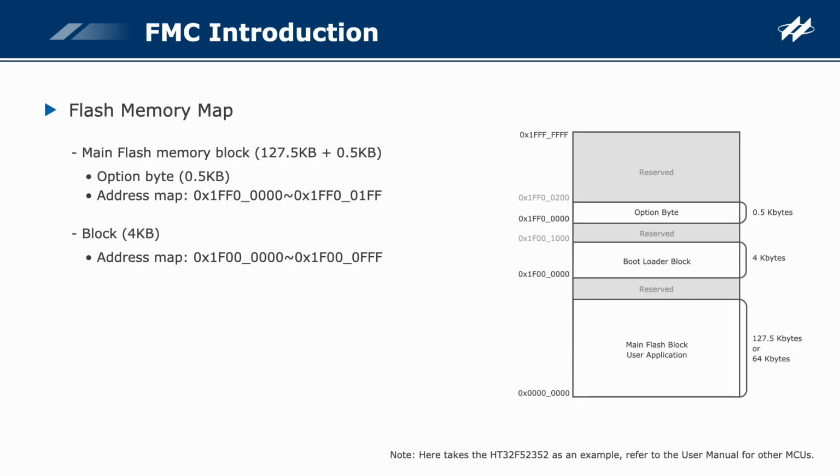As we know, the HT32 MCU address ranges from hex 00000000 to hex FFFFFFFF, 4 GB. Different MCU addresses map to different areas, where the addresses from hex 00000000 to hex 1FFFFFFF correspond to the code area and are mapped to the flash memory.